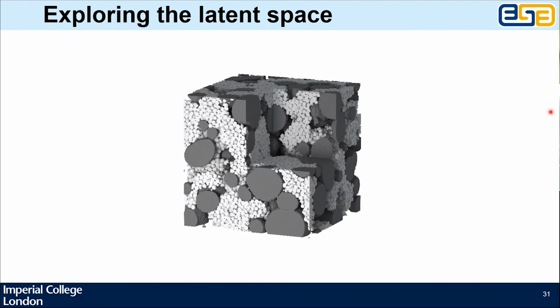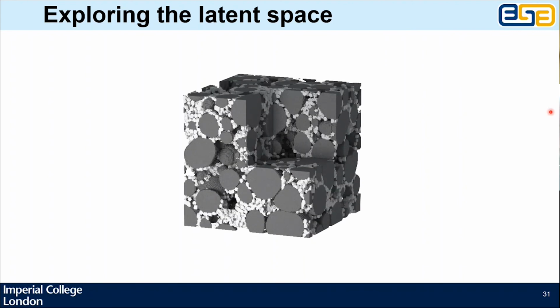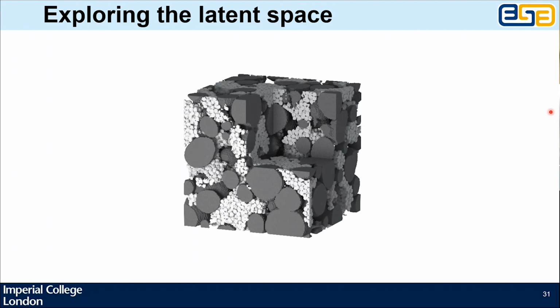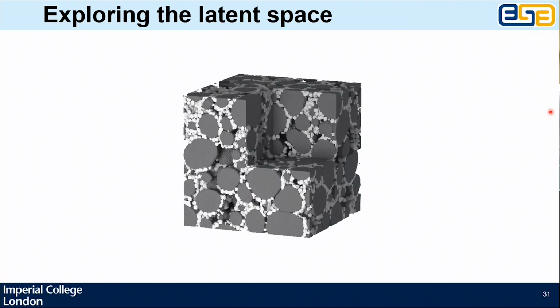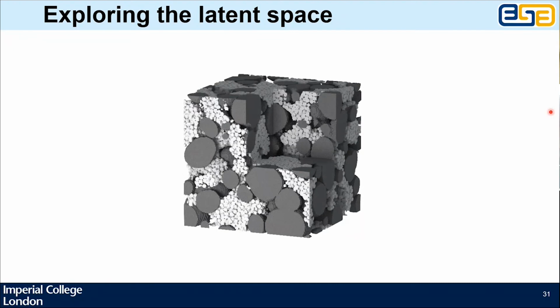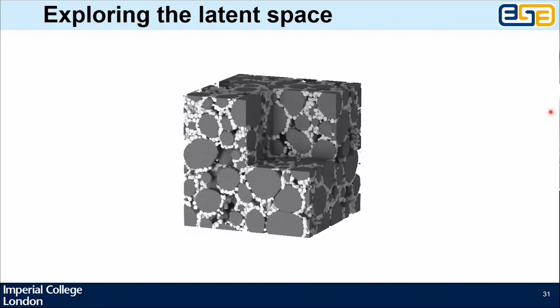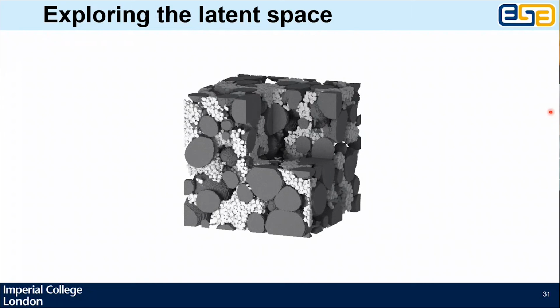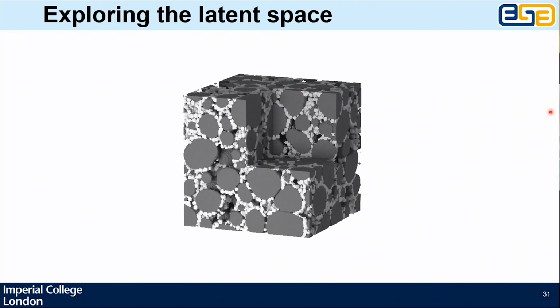Now, that doesn't necessarily tell you anything because I didn't tell you how long it took to render the video. But the point is this: the state-of-the-art battery manufacturing simulations, if you're going to simulate mixing, and you're going to simulate coating, and you're going to simulate drying, and you're going to simulate calendaring, these are extremely challenging simulations. And they tend to take on the order of many days on very large supercomputers to generate one, in my view, often not representative volume of some microstructure. Our GAN can look at image data, and once you've trained it on a normal office workstation for a few hours, it can then generate instances for you in a fraction of a second. So we've got 4 orders of magnitude speed up in our ability to generate and therefore explore the space of possible electrodes in this optimization cycle.